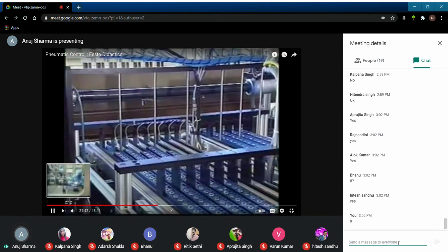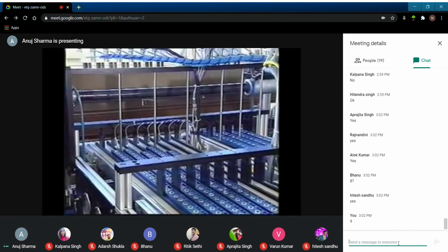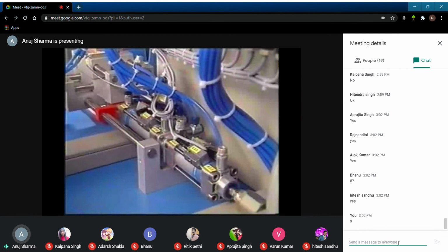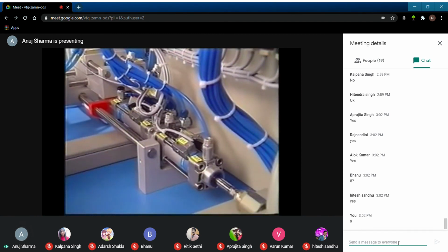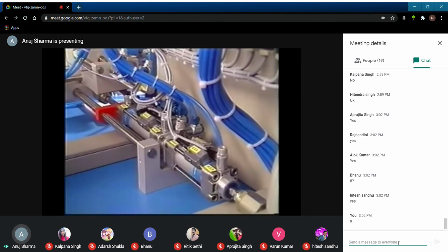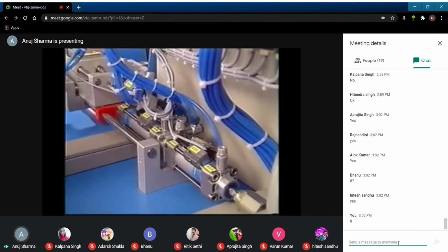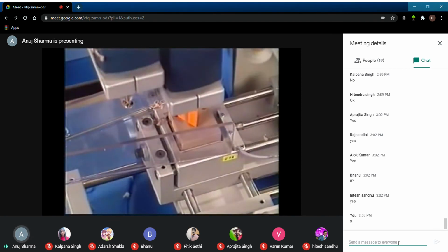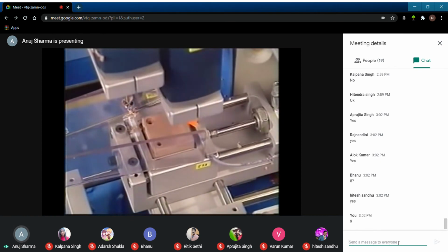Can also be achieved using cylinders, in this case with valves and multiple sensors. Another form of multi-positioning uses two double-acting cylinders joined together. If the cylinders are of different length, this design is capable of achieving four different positions. For example, the four positions are used in this machine to drill and countersink two holes.